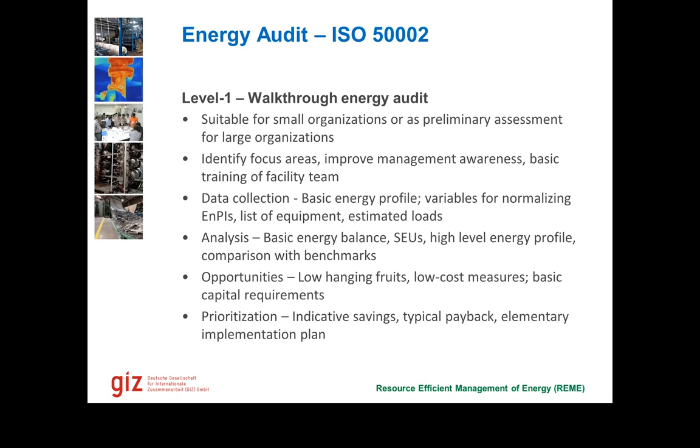Prioritization at this point could be only on the indicative savings because we are not doing any measurements here. And we could tell, for example, if a company replaces their lighting with energy efficient lighting, typically they save 20% or 30% with a typical payback period of 1 year or 1.5 years, for example. So this is all kind of a qualitative assessment rather than purely engineering assessment.